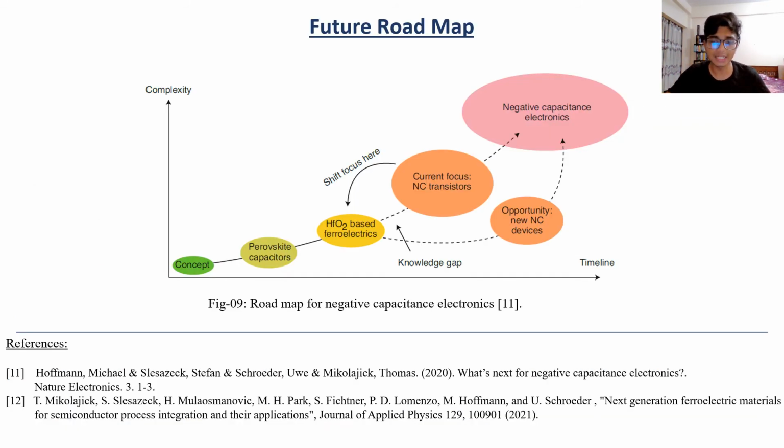While significant progress has been made in the basic understanding of ferroelectric negative capacitance in recent years, the development of practical devices has seen limited success so far. First, fabricating ultra-thin hafnium oxide-based ferroelectric films predominantly in the orthorhombic phase is still one of the biggest challenges for NC devices. Further, experiments on different ferroelectric or dielectric heterostructure capacitors have been going on to give us new insights into the domain structures, which strongly depend on the electrostatic boundary conditions.